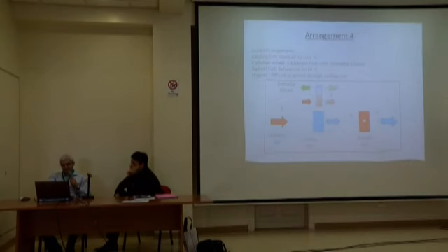We tried different configurations, and the one that gave the best results was to pass about 68% of the air through the recovery wheel. Definitely this depends on the amount of exhaust available, and to make this exchange between the bypass and the airstream and the exhaust airstream.